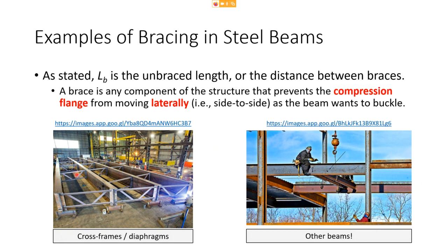So these elements, which we call cross frames, sometimes they're called diaphragms, but cross frames in this system, those cross frames are acting as braces for this beam, okay? So that's an example of a brace. Another example of a brace is just another beam framing into it.